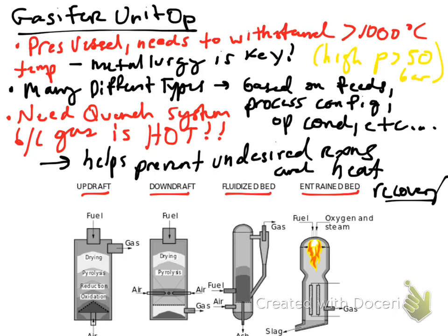When you perform these gasifications, you have residuals from your feedstocks. Tars are produced, ash is produced, char is produced. Basically, that's spent carbon, and that is deposited on the bottom, and then that's removed via usually a hopper system. And many times you can use that ash. Sometimes they use it, I believe, as maybe they can treat it to make filter-based carbons and stuff like that. They may be able to use it in electrodes and things of that nature, but essentially it's spent fuel, and it can't be used as fuel again.